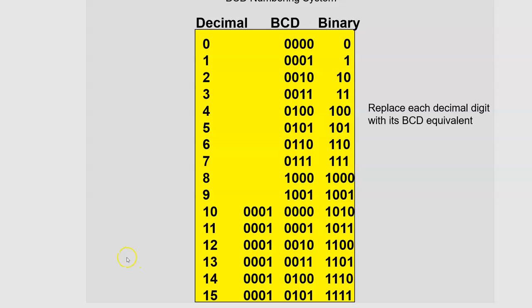One 7-segment display will display a 1, and the information to display that 1 will come from this. And the second 7-segment display will show the 2, and the information to light up to give the 2 will come from this. So for each decimal digit I need 4 bits of BCD code to express each decimal digit.